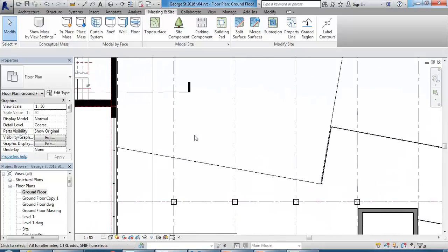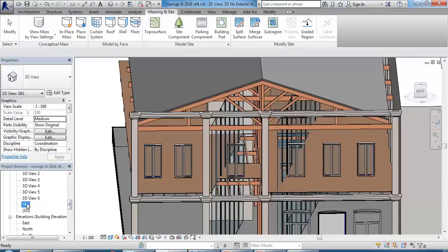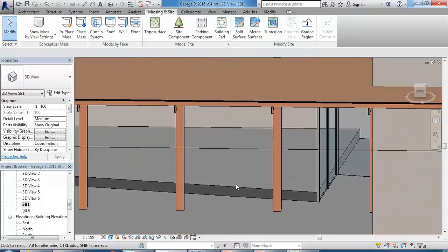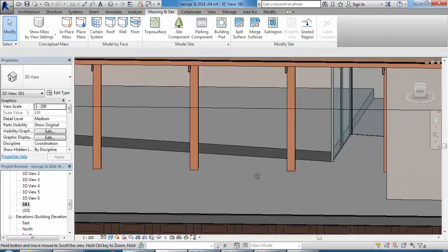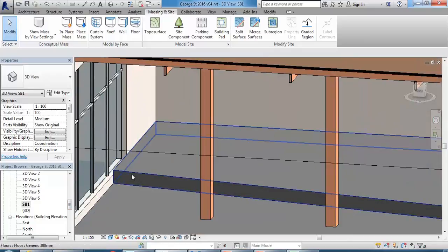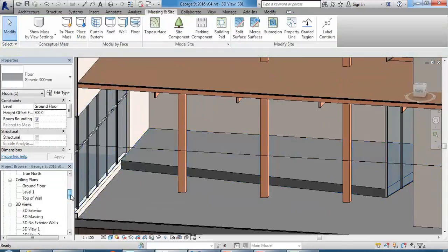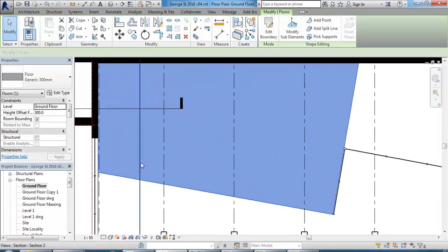Okay, so I'm just going to have a look at the ramp tool with this elevated floor that I've added, and so I'm just changing to a section box view there. So you can see that I've added this floor that's been raised 300mm above my main floor level, and so I want to insert a ramp in there for disabled access, and so I'm going to do it from the rear. So I'm going to go into plan view and do some of the working out there.